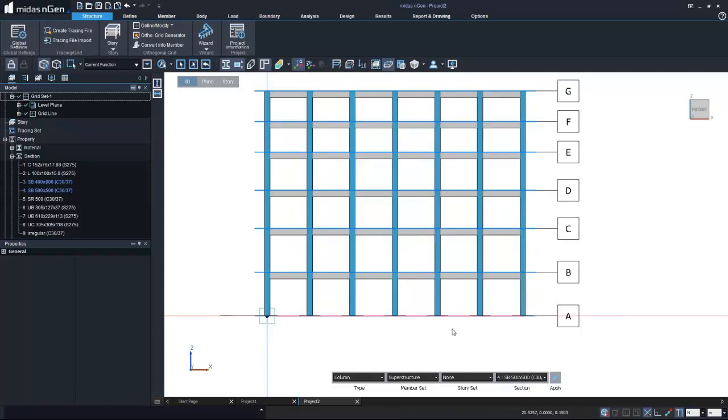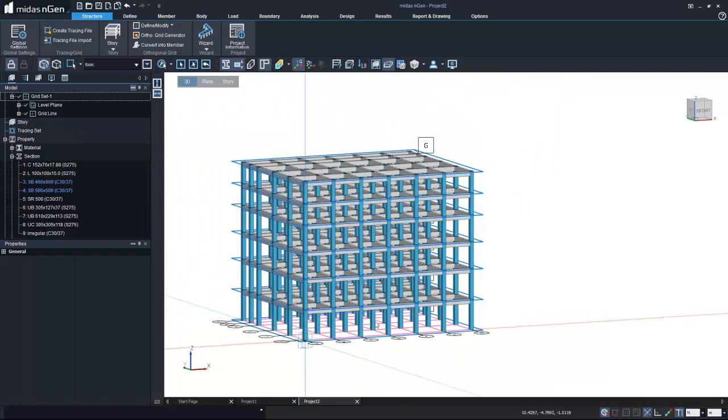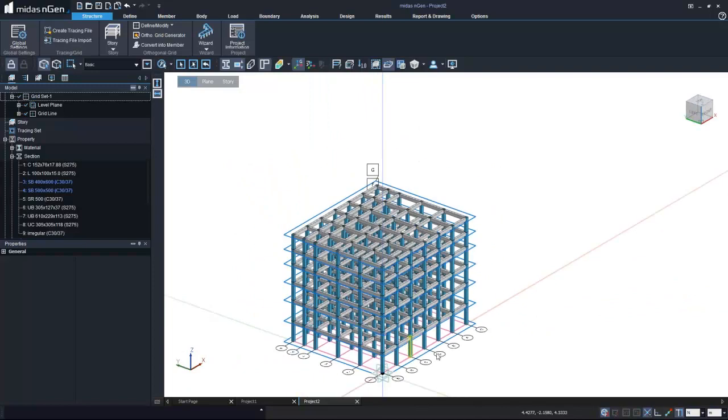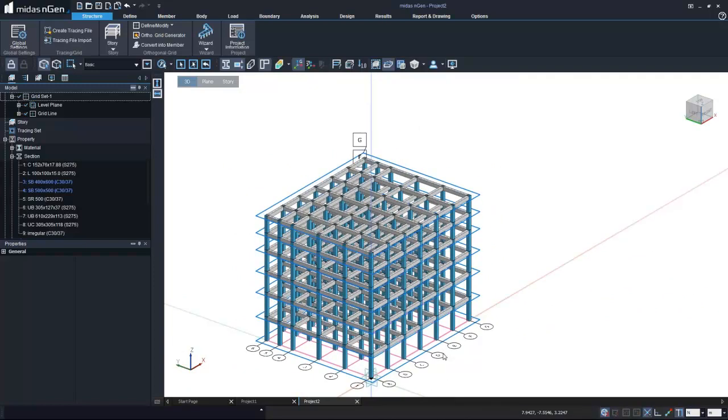Click on apply. And as you can see, this is not just because I'm in front view; I'm not just selecting whatever I see, I'm selecting everything that is there with me. It actually makes it easy for us to do the modeling in this way. So by two definitions, by two clicks, I was able to create the beams as well as the columns. And similarly, I can go ahead and create my walls.